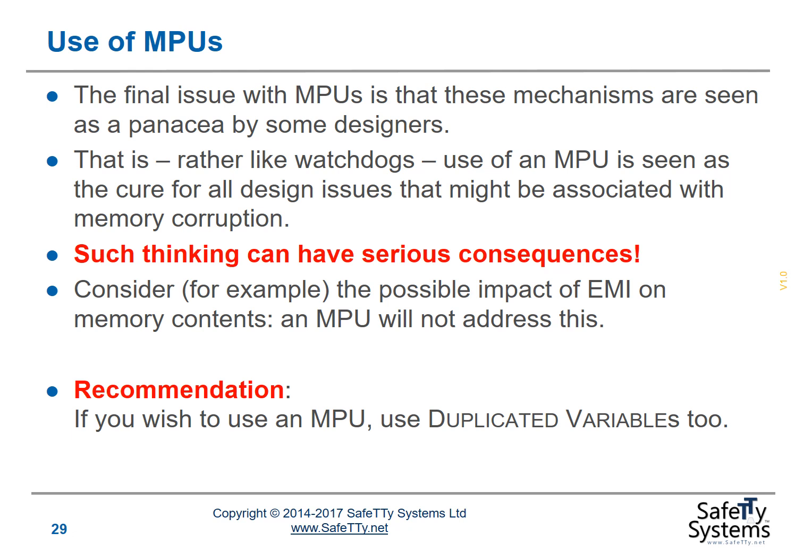If you consider, for example, the possible impact of EMI on memory contents, a memory protection unit will not address this. The kind of techniques we've been using with duplicated variables will detect such corruption. If you wish to use an MPU, we suggest you use duplicated variables too.